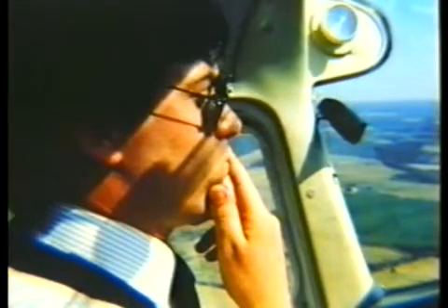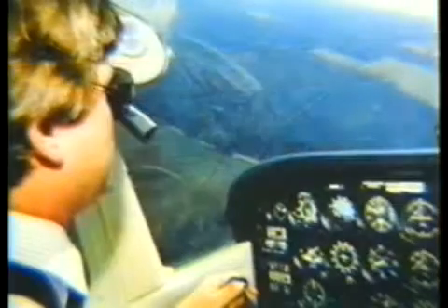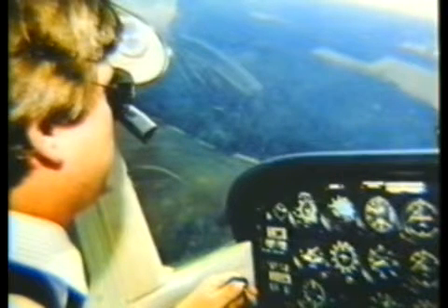One other part of your pre-landing routine should be to get in the habit of saying to yourself, "Now let's see, if I have to go around, this is what I'll do." And then you review the actual steps you'll take, because if you do go around, you'll only have time to do. You won't have time to plan. I'd like to point out that what you're actually doing here, of course, is taking the first steps toward a possible go-around before setting up your initial approach. And that's a good thing to do.